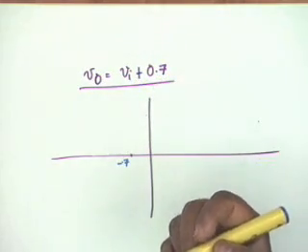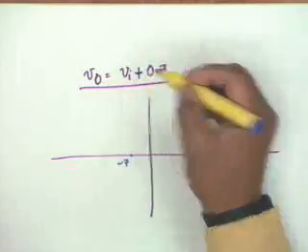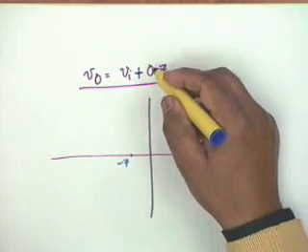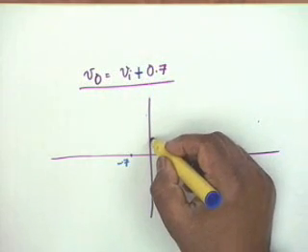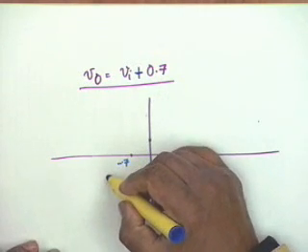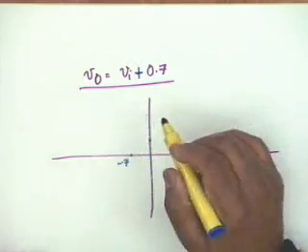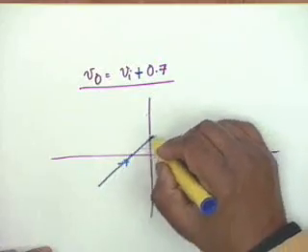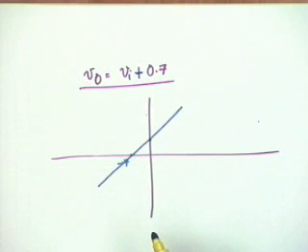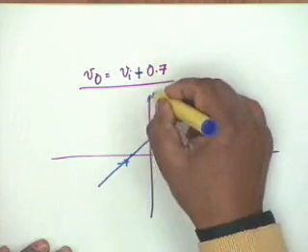I made a mistake. It was the previous story. Previous story was Vi minus 0.7. Now it is Vi plus 0.7, and therefore when Vi equal to 0, V0 is this. Thus, the curve now has no dead band. Because we have shown that whether you go through Q1 or Q2, the relation is the same, the curve now goes like this. Okay, there is no dead band. This is Vi and this is V0.